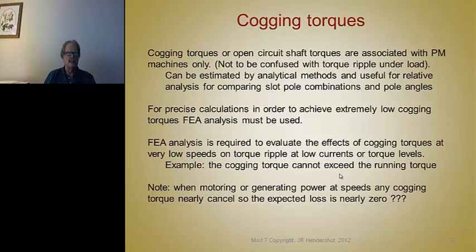Because a stator with 12 slots has 30 degrees per slot. So 2 teeth is 30 plus 30, that's 60 degrees. Well, that's the same angle as a 2/3 pitch 4-pole motor, 60 degrees. So that means that every edge lines up. That has the maximum cogging torque. Now, if you increase the pole arc from 60 degrees to 65 or 70 degrees, your cogging torque is cut in half, but the frequency's doubled. Now you only have one edge of a magnet lining up with a slot. And since there's 4 magnets, one edge is 4 slots, so there's only 4 reluctance alignment positions of the rotor to the stator. So that's just enough to show you what the effects of the slot and pole combination can be to minimize cogging torque.